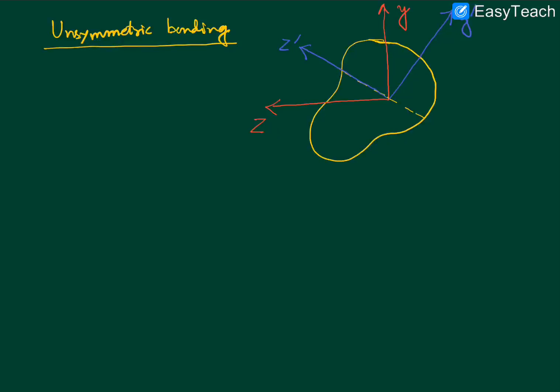Surely there will be some fibers of the beam which will be in tension and some fibers of the beam which will be in compression. And because we are considering pure bending of beams, it is natural for us to expect that there will be some flexure formula which will give us a distribution, or some sort of answer, for the sigma xx. Right now we don't know what that answer is, but we only want to develop some kind of intuitive or physical feel for that sigma xx.